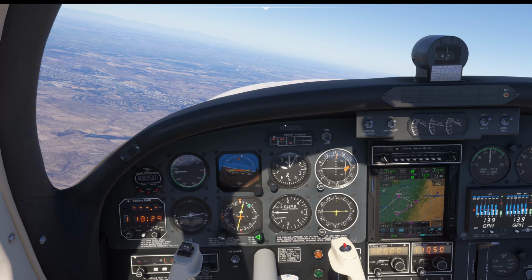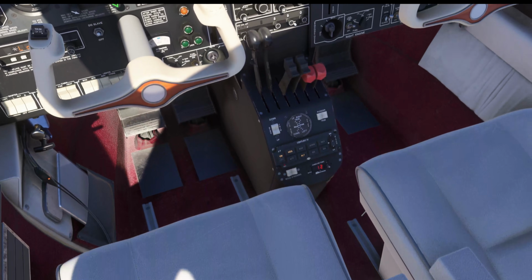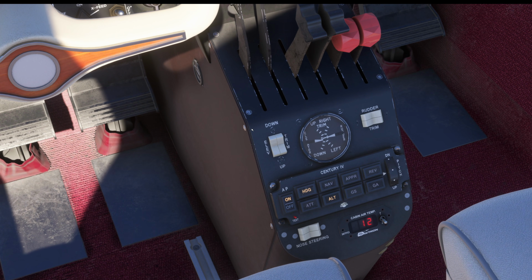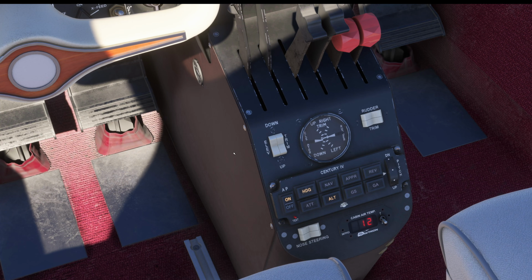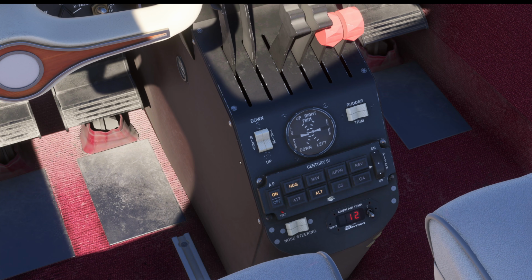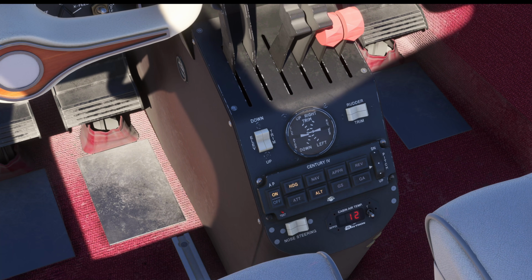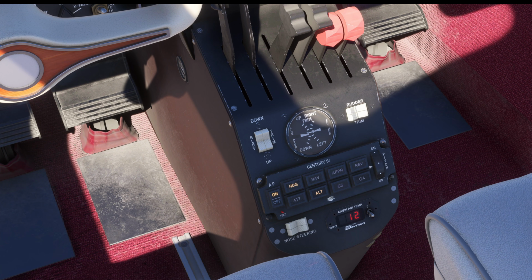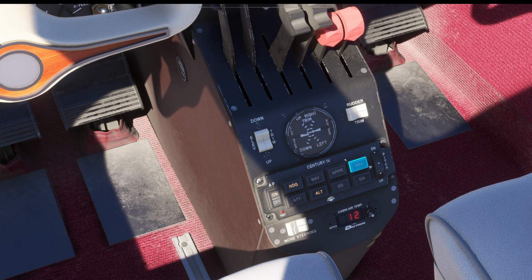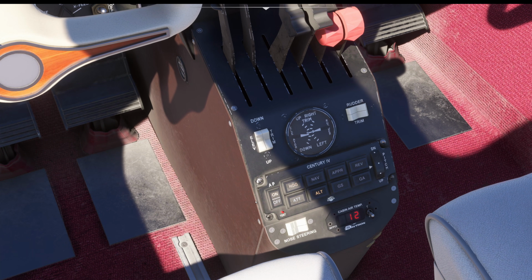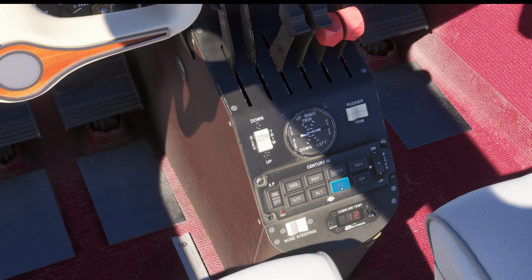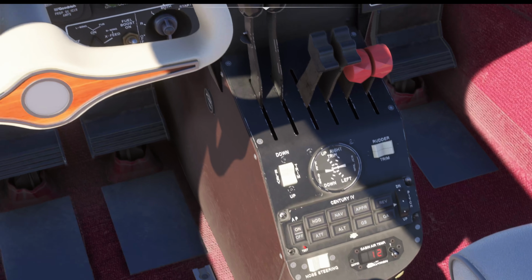The Century 4 itself is an autopilot designed in the late 1970s. And despite its age, it's a quite capable device with basic modes that should be familiar to those flying other aircraft in Microsoft Flight Simulator. It has several navigation modes like heading, nav, approach, reverse. And in the vertical channel, it can hold attitude, altitude, or follow glide slope down to the runway.